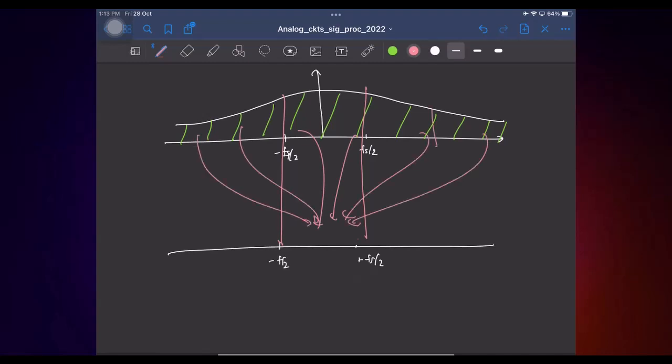Samples are independent of each other, so we are directly able to add the powers. But this doesn't mean that the output samples are independent. You are assuming that this will all add up and form white noise, so that samples will be independent of each other. That need not be the case.